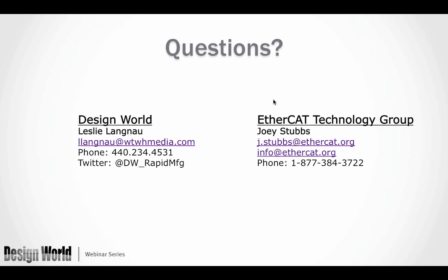So you typically don't have to do timestamping with a push button from an operator, for instance. So no need to use distributed clocks for generic I/O, but for time critical or time sensitive applications, or for getting rid of dedicated sensors on the network and just going to dumber photo eyes and other types of commodity sensors, then DC enabled devices make a lot of sense.